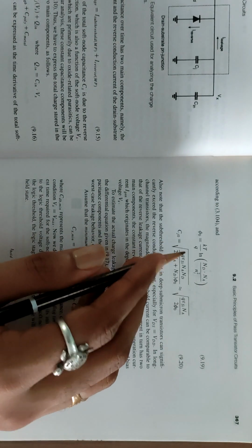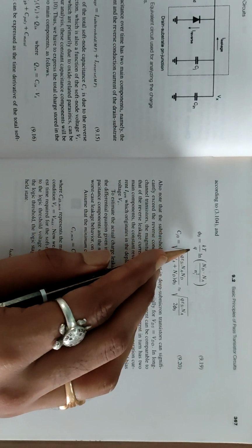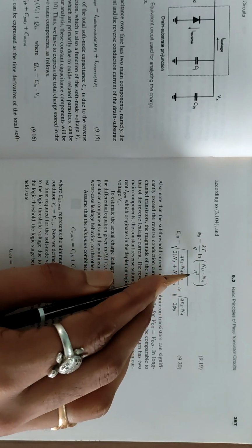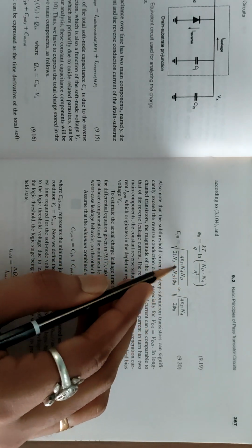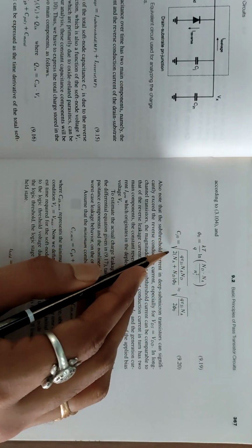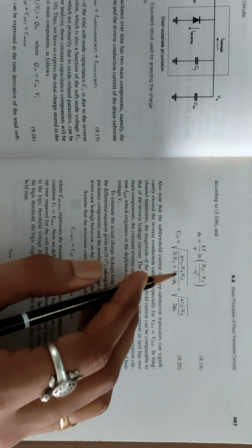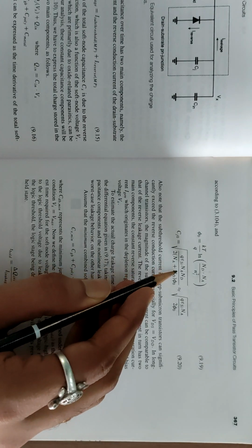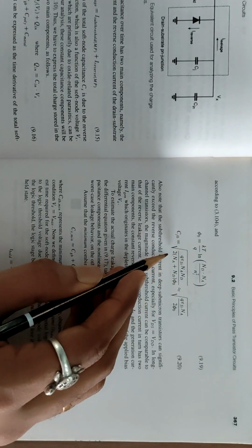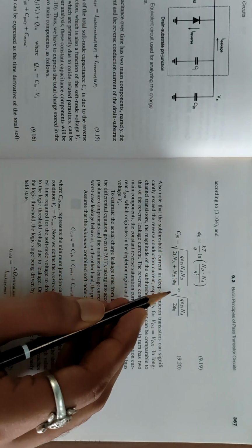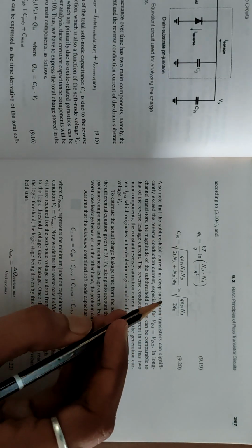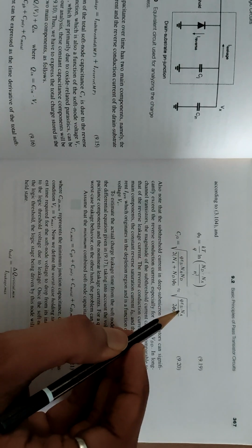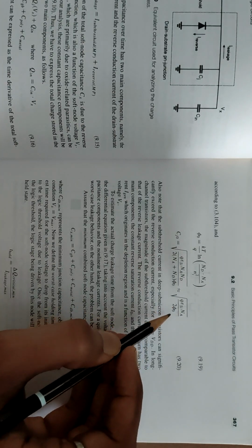According to the equation, phi0 equals kT/q times the natural log of Nd times Na over ni squared, and Cj0 equals the square root of q epsilon_si Na Nd over 2(Na plus Nd) phi0, which is similar to the square root of q epsilon_si Na over 2 phi0.